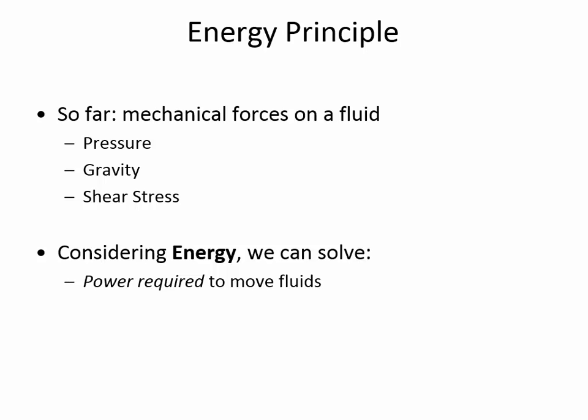So in the energy equation, what we're going to be doing is looking at losses of energy, no longer assuming that no energy is lost as water flows from one point to another. I mean, you saw it in the lab when you worked with the Venturi. You saw that the energy grade line wasn't flat. It went downhill. It was pretty flat, but we were talking about a section of pipe that was a foot. And so you saw physically with your eyes, due to the piezometer tubes that were coming out of that Venturi, that on the upstream end there was more energy than on the downstream end. And so we need to consider energy losses. And when we do that, we can calculate how much power is required to move fluids from place to place.